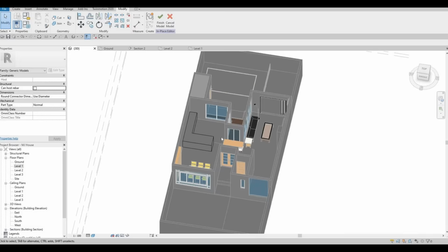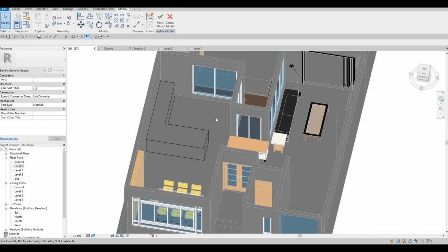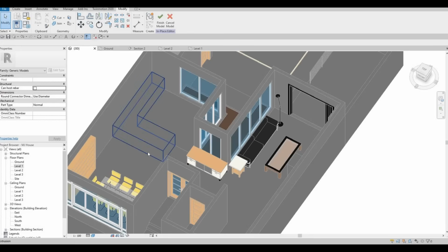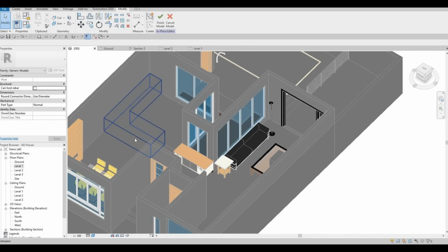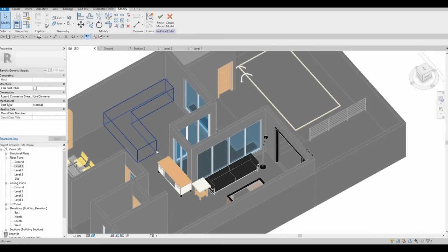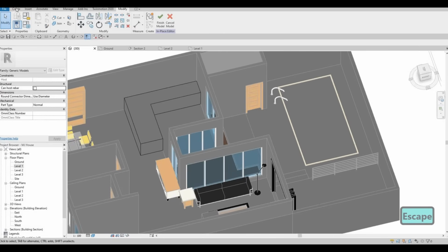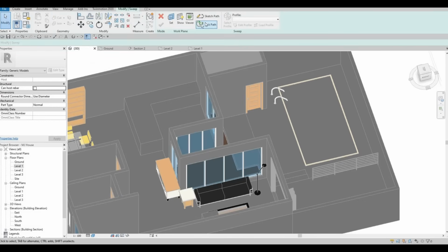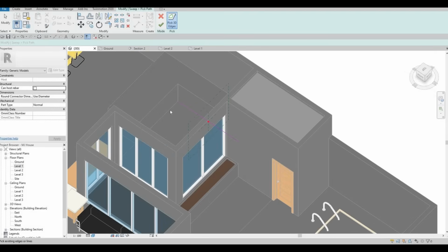So that looks good. We have enough space to go right here. What I'm planning to do is I'm probably not going to add anything right here in terms of kick plate. I'm gonna put the kick plate in here on this side. So to do that, I'm gonna click on create and then void sweep and then choose the path. So pick path and then select both of these.